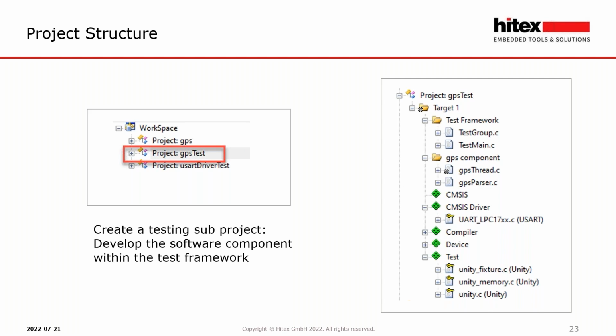And at the bottom there, we have the test project, which is the validation framework for the UART, so that we can run the test framework to check that our hardware is working before we integrate it to the component code. So here we have a hierarchy of projects that are testing the board layer, the component layer, and then integrating into the final project. And if we discover any problems at any point, we can fall back to the sub-projects to try and resolve the problem. So again, it gives us more options within our debug environment.